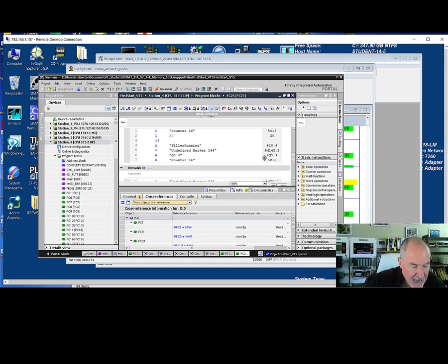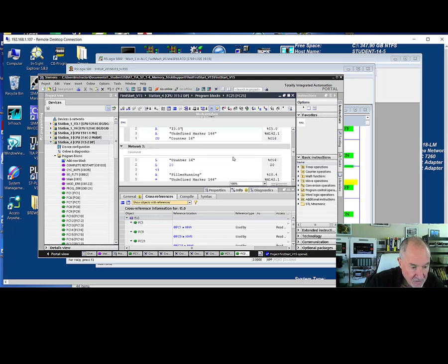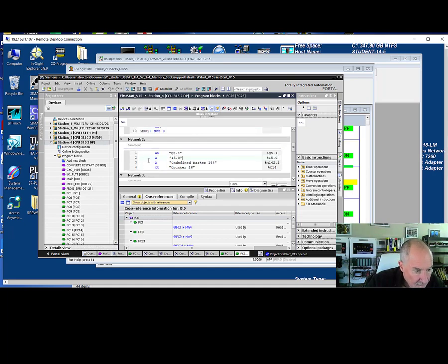And you'll trace this back as far as you need to, right? And that was in network 3, and then when I went to network 2, I found a counter. The counter was counter 16. And counter 16 is made to count by I5.0, and Q5.4 has to not be on.